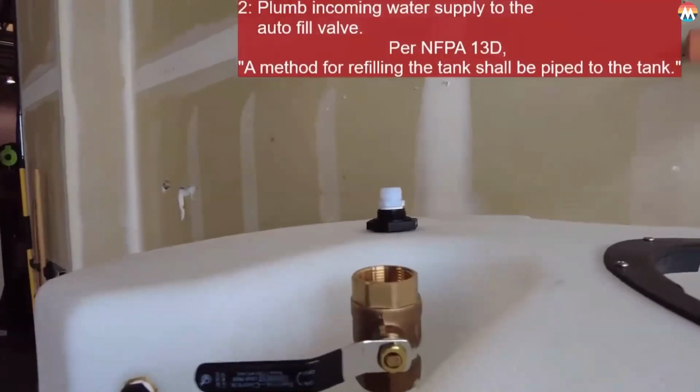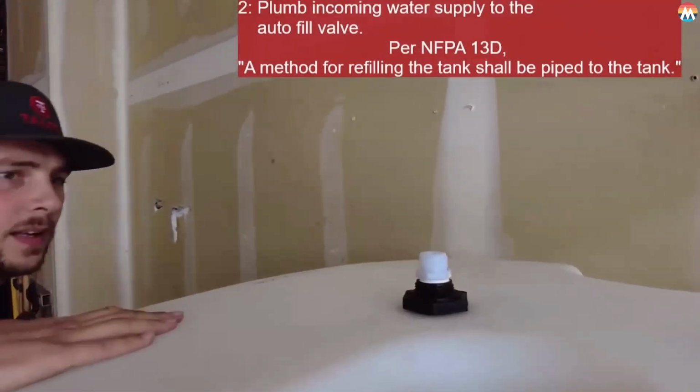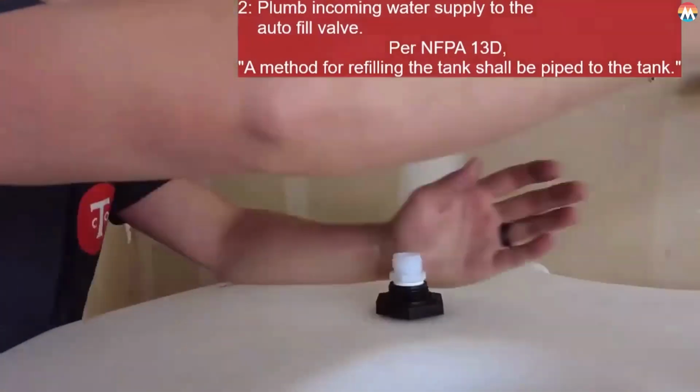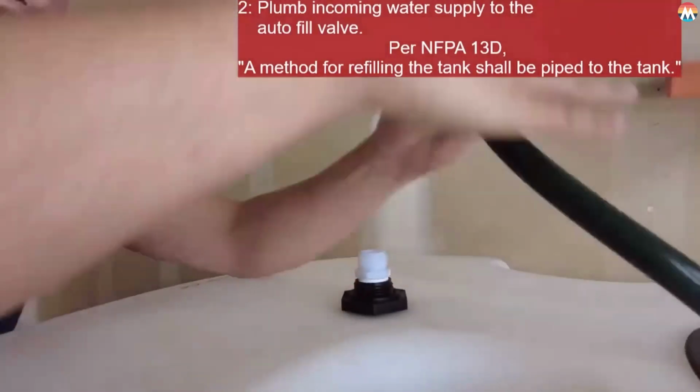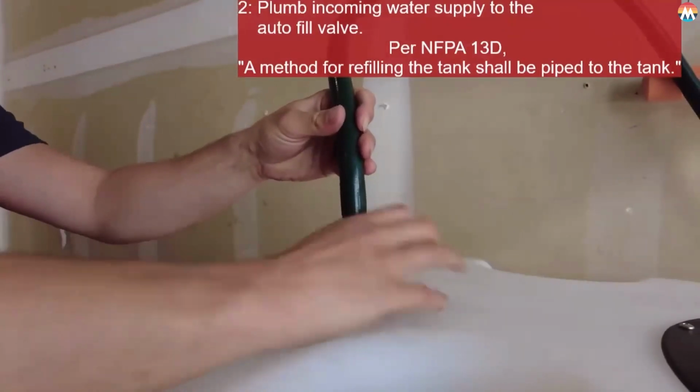Next, we're going to connect the incoming water supply to the autofill valve. Today, we're just using a garden hose for demonstration purposes, but NFPA 13D says that a method for refilling the tank shall be piped to the tank.